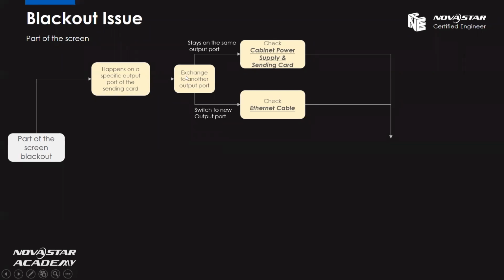And if we exchange to another output port and the issue switches to a new output port, this means there is no problem with this output port. So in this case, we need to check the Ethernet cable to see if there are some problems.